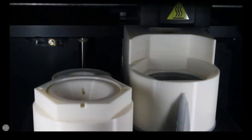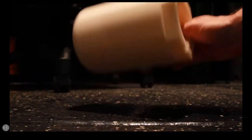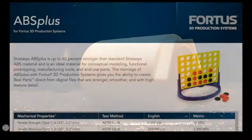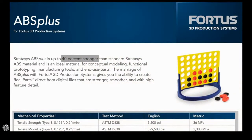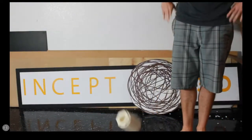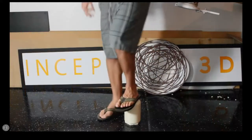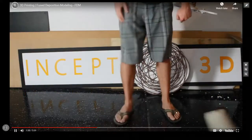Even within Stratasys, the guys who manufacture the fused deposition technology, they have varying levels of material based on how sophisticated the machine is. Things like tensile, impact, and flexural strength will vary depending on the machine at hand. Our material is engineered for the Fortus production systems, which Stratasys advertises is 40% stronger than their standard ABS. So the important takeaway point is not all ABS is alike, by far, and we encourage you to look at the material specifications before ordering an ABS part.